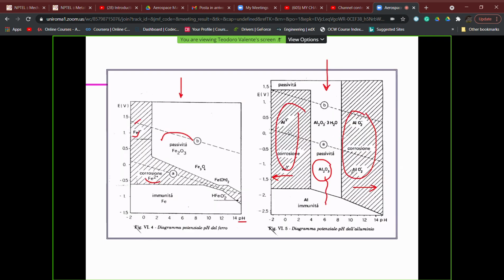So this is the way in which thermodynamics gives us a response, essentially by giving us the possibility to use the Pourbaix diagrams, which are based on the Nernst equations for the cathodic and for the anodic reaction, and for which we must not do any work, because the atlas of the Pourbaix diagrams is all available.